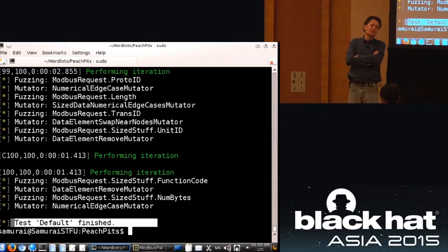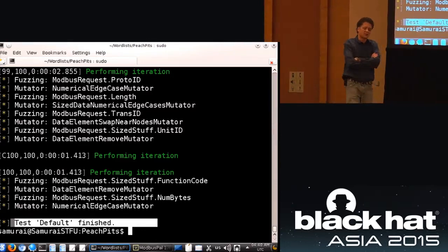So the question is, because Modbus is so simple with no security, what can we do to try to improve the security of Modbus? Well, the biggest thing we need to do is look at the interim. What can we do right now? And then what can we do about the future? So right now, the best thing we can do if we have something like Modbus is, number one, keep the attackers away from Modbus.